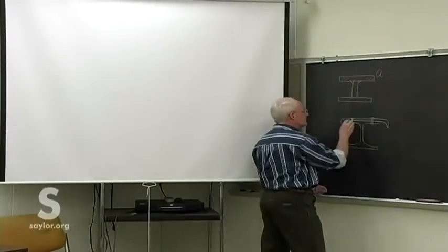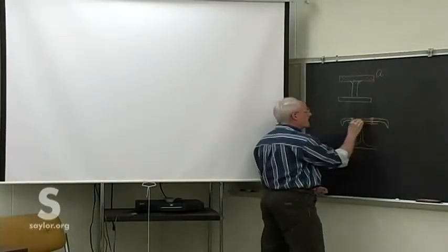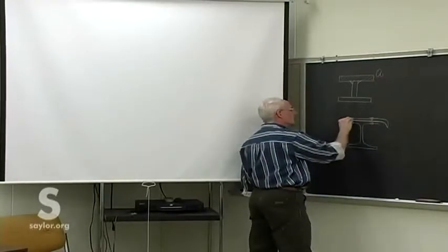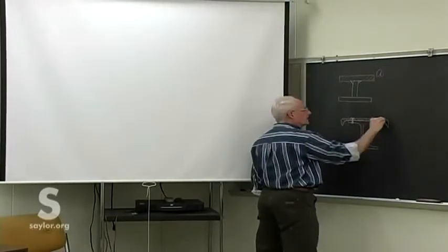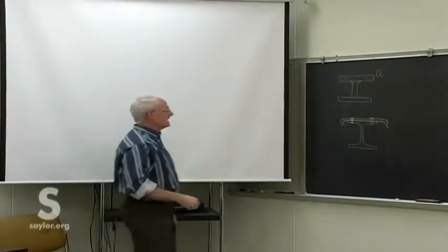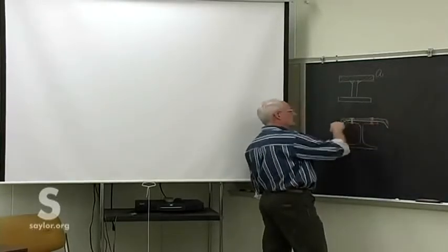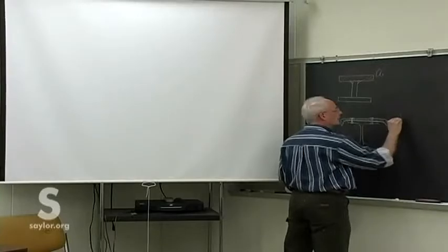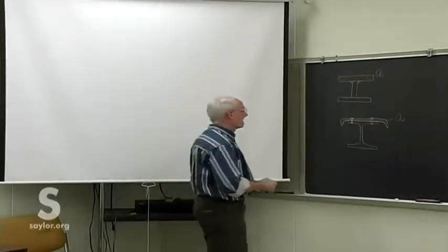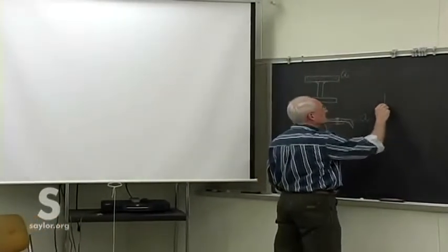Now the plane of concern is this one here, and the area beyond that is this entire area of the channel. Even though some of the channel actually hangs below that plane, it's not available right at the plane. We have to take in the whole area to account for this longitudinal shear down the whole piece. So that's not as obvious as it might be for some of these other ones.